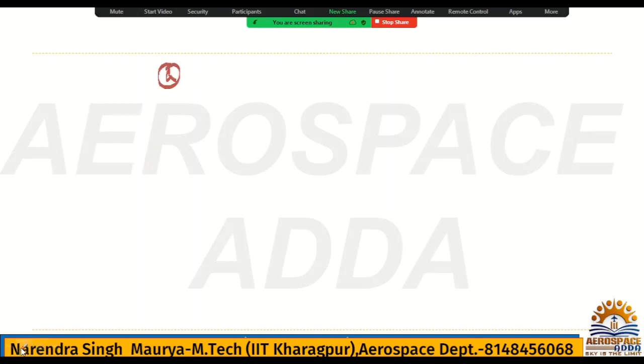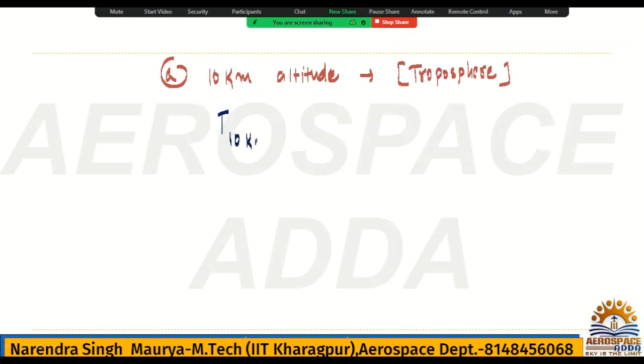How? Check. At 10 kilometer altitude, which is the troposphere, we need to calculate temperature and pressure. How to get this? In the troposphere, as I taught you in performance, T equals T sea level minus lambda into h. Better not to say T infinity here because we have denoted T infinity as the free stream.